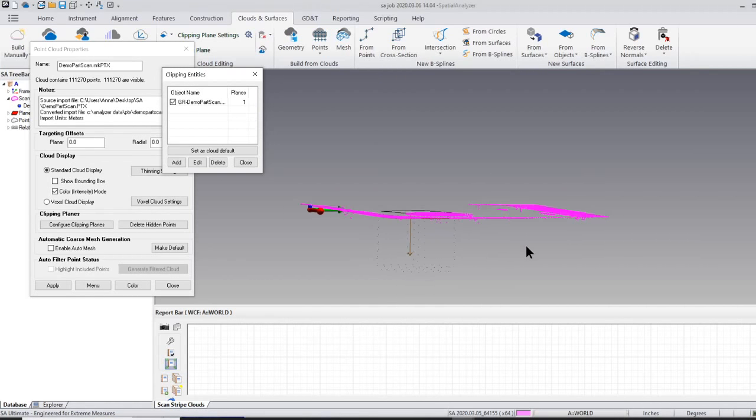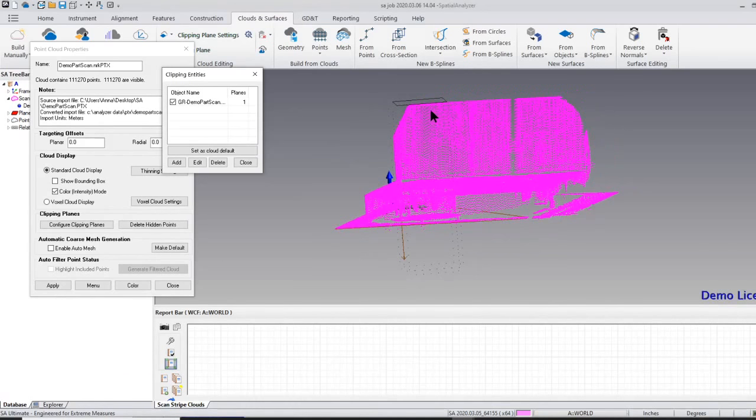So I say clipping plane, but it really gives us this opportunity to clip by volume. And right now, it's using this top side of this cube to clip, which is not what I want to clip. I want to clip in the opposite direction. So if you can rotate around, I can see that if I hover around, I can use these to control my clipping volume.